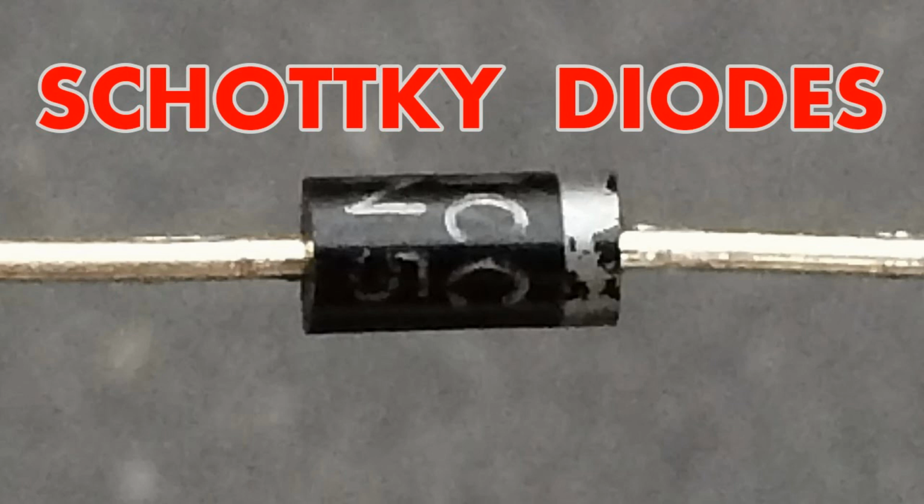These diodes have even faster reverse recovery times and are used in applications where very high switching speeds are required. Silicon carbide (SiC) diodes. SiC diodes offer higher efficiency and temperature performance, making them suitable for high power and high temperature applications. Power rectifiers find applications in various electronic devices and systems, including power supplies, battery chargers, motor drives, inverters, and rectifiers for electrical grids.